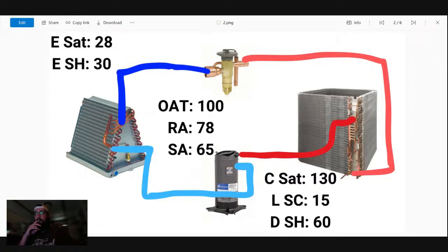Well, okay. So let's say it was wrong refrigerant. Then the test procedure for that would be a standing saturation. So really the best thing you could do, in my opinion, would be to recover the charge out, or at least take enough of it out into a small recovery bottle to get some actual liquid in the system.